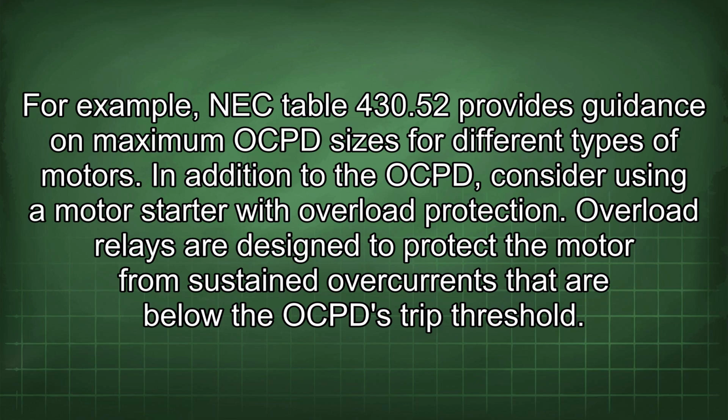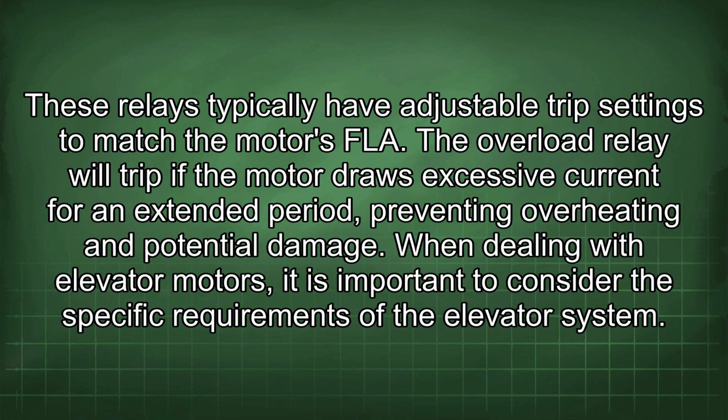In addition to the OCPDs, consider using a motor starter with overload protection. Overload relays are designed to protect the motor from sustained overcurrents that are below the OCPD trip threshold. These relays typically have adjustable trip settings to match the motor's FLA. The overload relay will trip if the motor draws excessive current for an extended period, preventing overheating and potential damage.